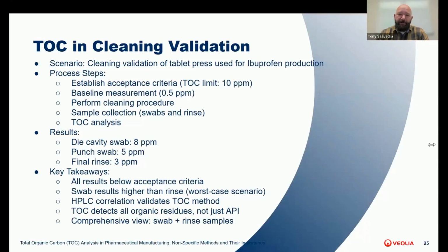First, we need to establish our acceptance criteria. Based on the toxicity of ibuprofen and the surface area of your equipment, let's say we've calculated our TOC limit is 10 parts per million. Next, let's take a baseline measurement. We measure the TOC of our cleaning solution before we start. Let's say it's 0.5 ppm or 500 ppb. This gives us a starting point.